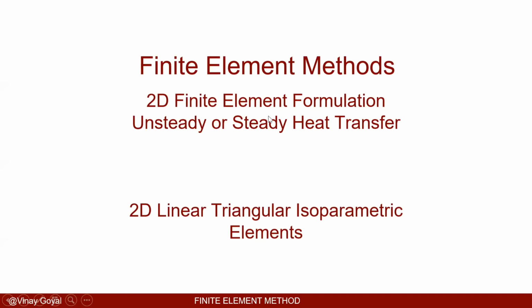And I hope you saw the powerfulness of isoparametric elements. They allow us to use the same shape functions for every element. The integrals are also done over a standard domain. And the derivatives of the shape functions are the same for every element. The only thing that contains the geometry of the element is the Jacobian. And that's very easy to calculate.